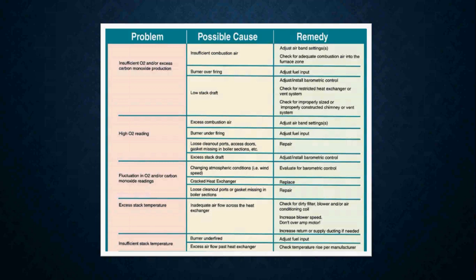So you're going to want to adjust the air band. You're going to want to adjust the fuel input maybe, or obviously repair the gasket or whatever door might be missing or something like that.